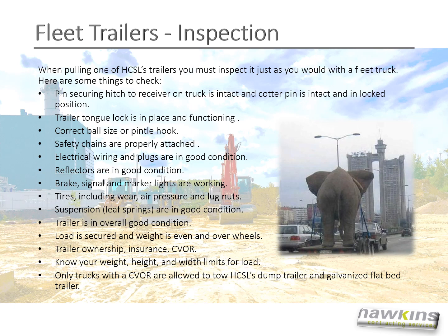Make sure reflectors are in good condition. Make sure brake lights, signal lights, and marker lights are working. Check the tires, including wear, air pressure, and lug nuts. Check the suspension to make sure it's in good working condition. Take a look at the trailer. Is it in overall good condition? Make sure your load is secured and weight is evenly over the wheels.